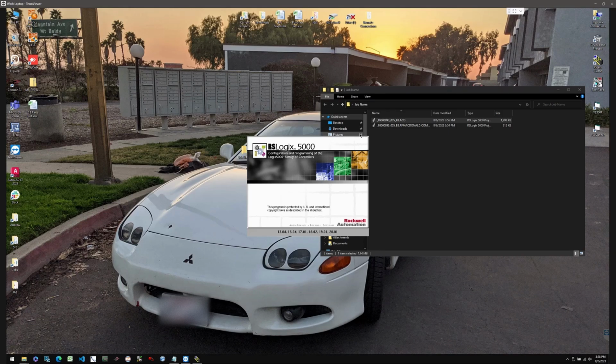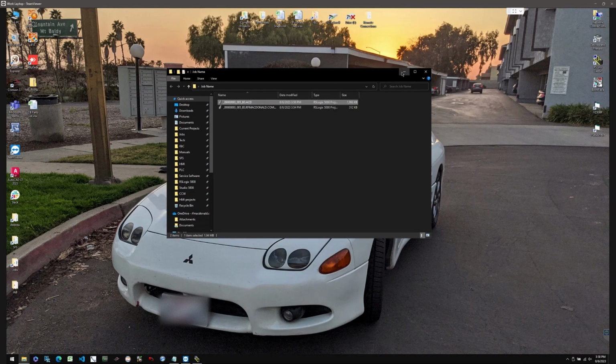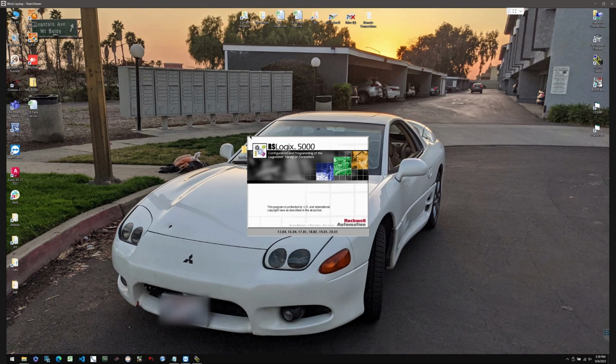So like I said, it's pretty simple, straightforward. The video is kind of long, I just wanted to show a few things. But the main things are just make sure that you set your IP address before you connect to anything, so you don't cause any communication problems for the customer or anything. And then just make sure you check communication and double, triple check what you're doing, whether you're uploading or downloading the program, and just make sure that you're doing it correctly so you don't cause any issues. And that's pretty much it.